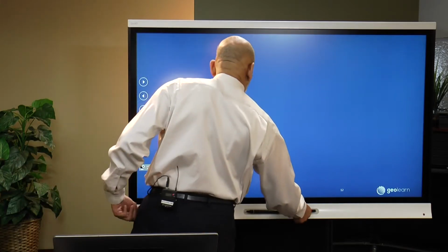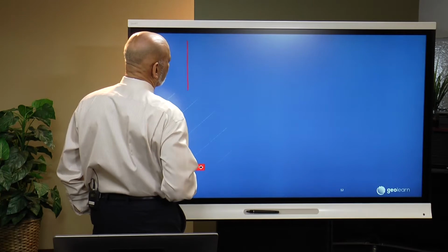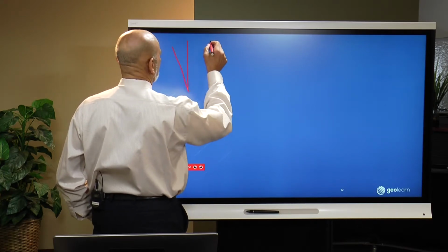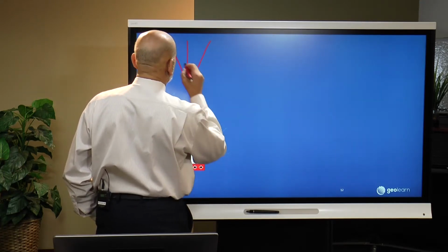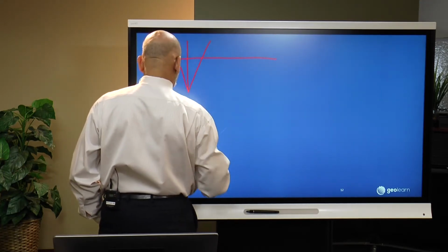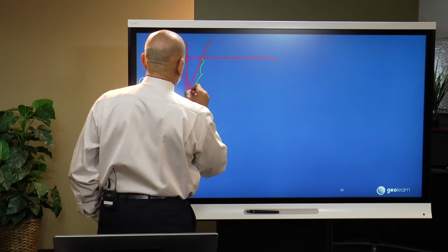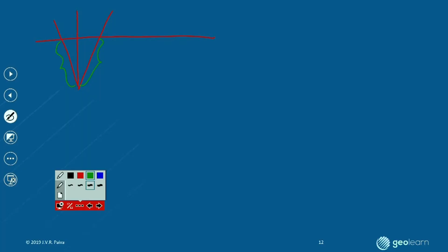For example, one of the most common things is the rod not being held vertically. Because if the rod is leaning back, or if the rod is leaning forward, and you have a horizontal line of sight, I think you can see that you might have different readings depending on how far from the vertical your rod is at the time.